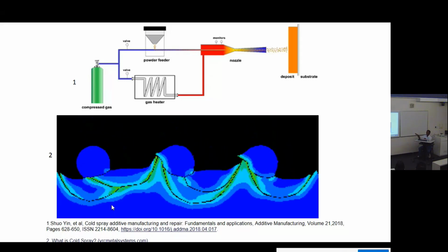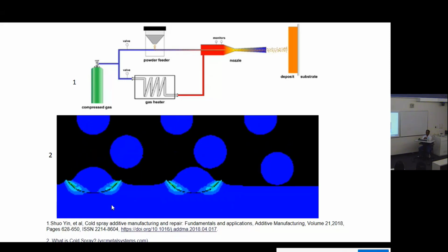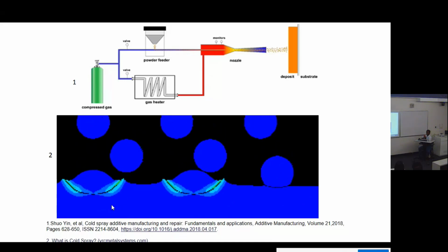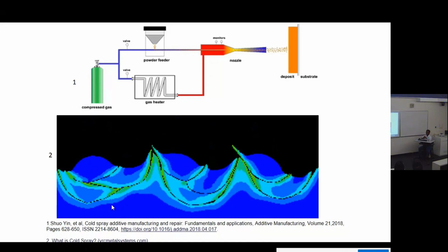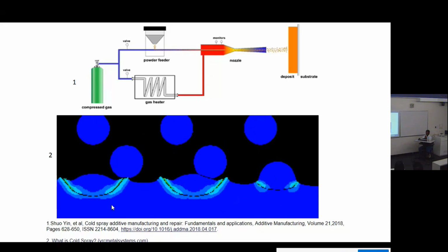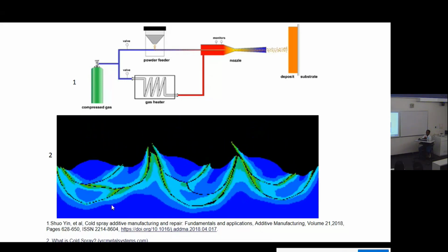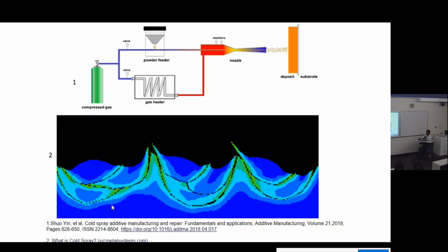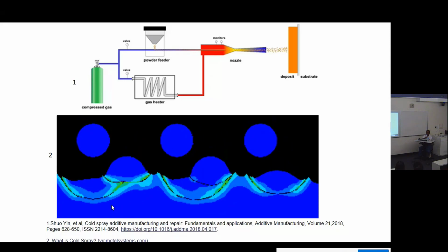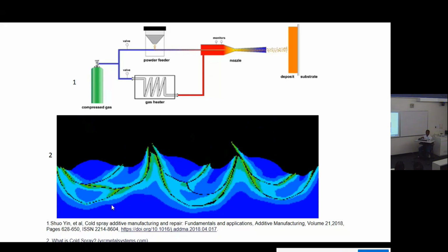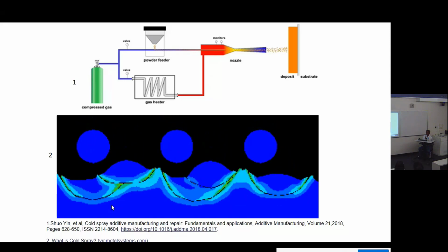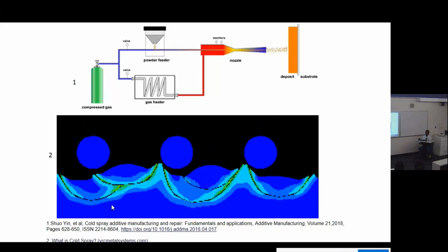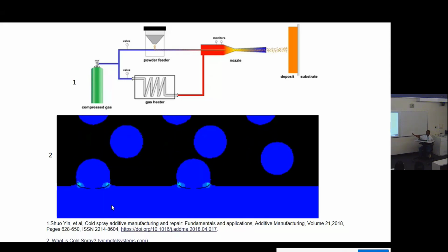So there are many other parallels to this idea. If you have explosive bonding, you have one plate and another plate on which an explosive material is put and then detonated. If it hits the next plate at very high speeds, it will actually form a bond. And there is friction welding. And if you drive a car, the car wheels are made by flash butt welding. Again, it's made in completely solid state in 20 seconds. It's all done, your car wheel. So all this is done completely in solid state.